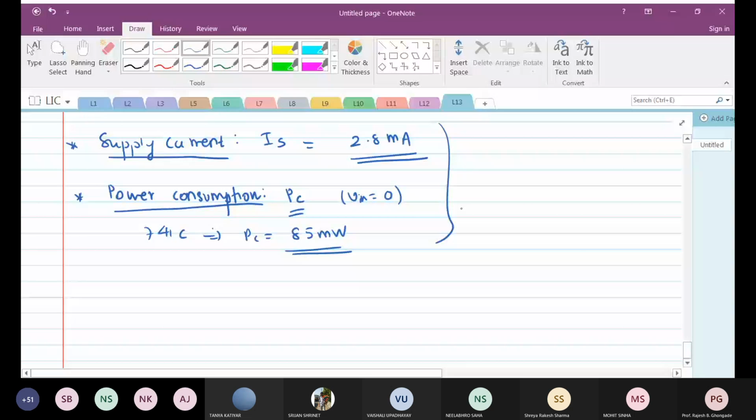Please remember that whenever you design any circuit, any application, power supply is one of the most important and critical components. And we must have a very strong power supply. Strong in the sense that the power handling capacity or the current sourcing capacity of that power supply should be sufficient to operate your design. This is most of the time called the power budget.